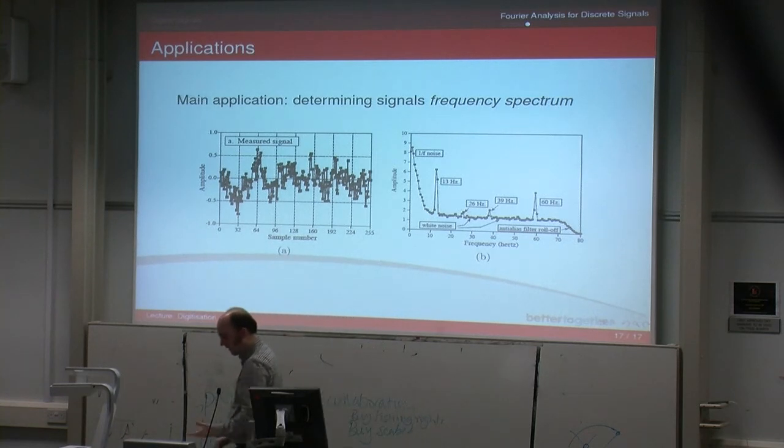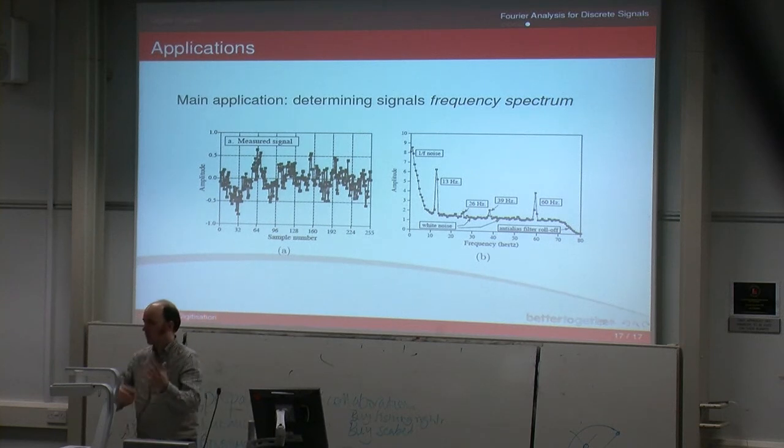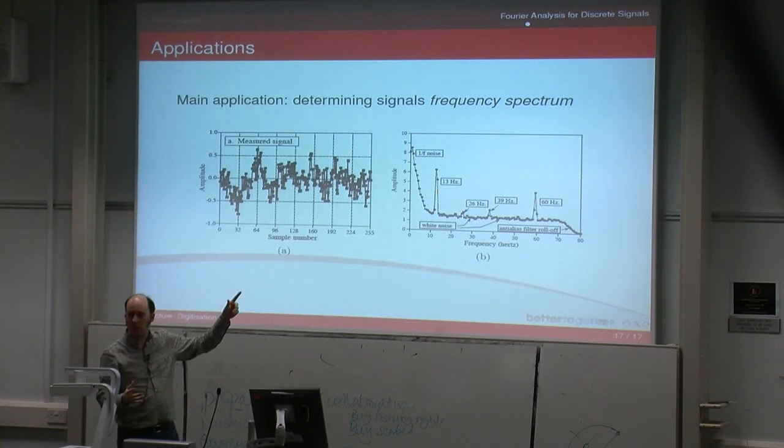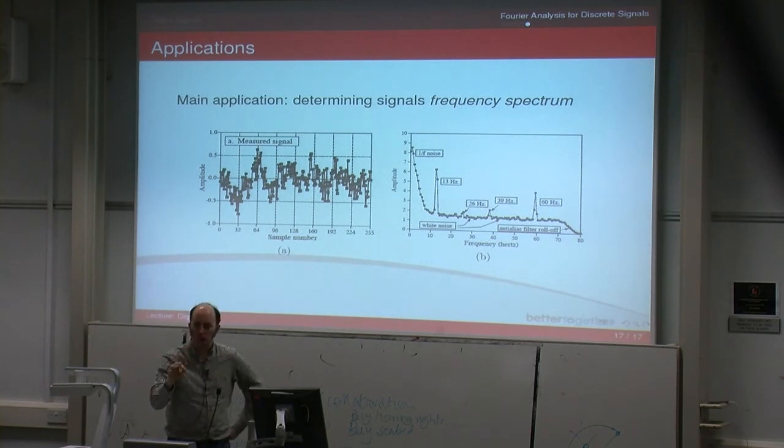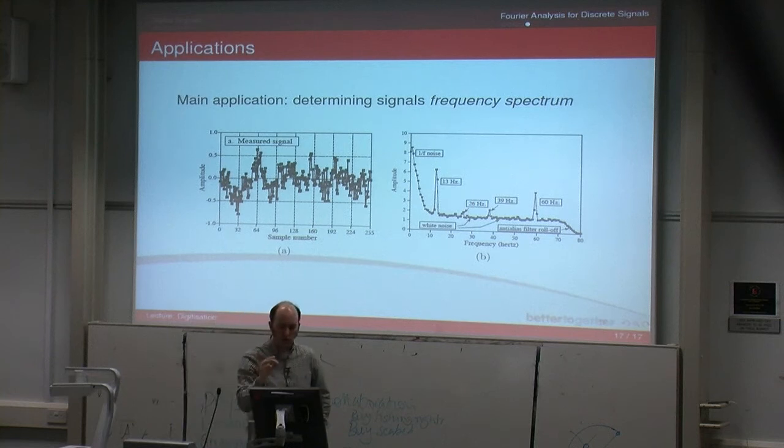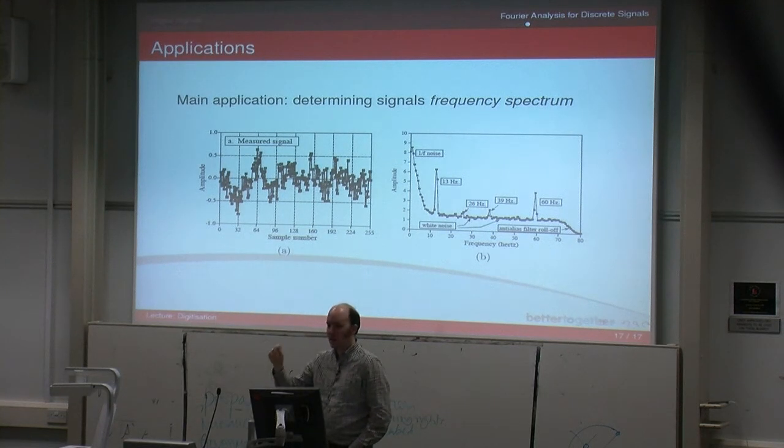If you're doing a final year project that involves something that moves and you're measuring how far it moves, you're going to be dealing with these sorts of issues. If you've got something that vibrates backwards and forwards, it might have a random signal. You have to bear in mind that when you're sampling it, you need to make sure that the frequency you're interested in is half of your sampling rate. If your frequency and the sampling rate are about the same, you're going to end up with possible aliasing, which is obviously a bad thing.